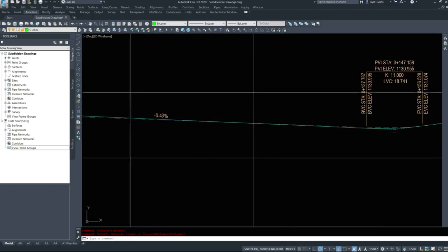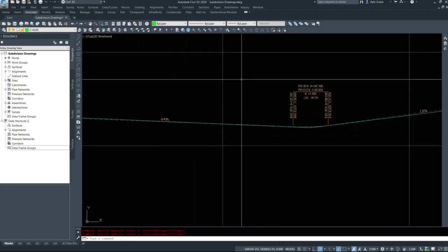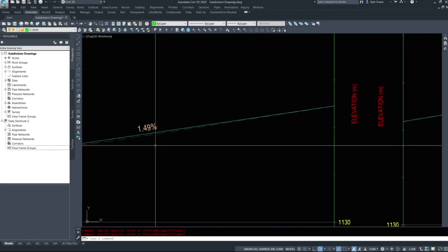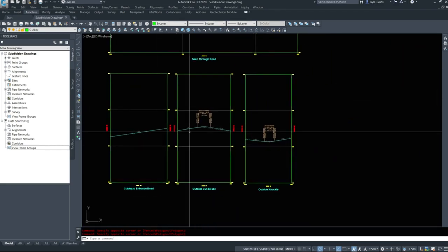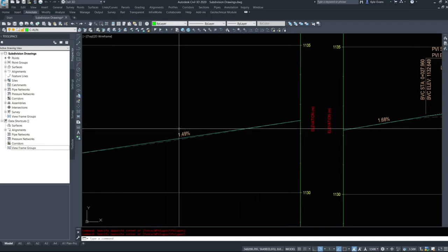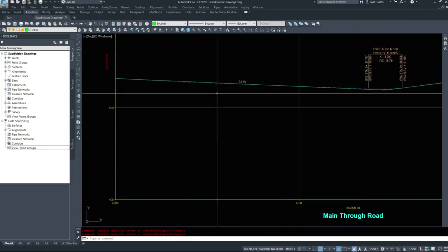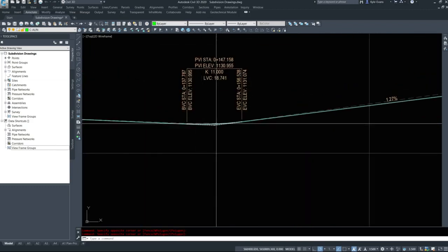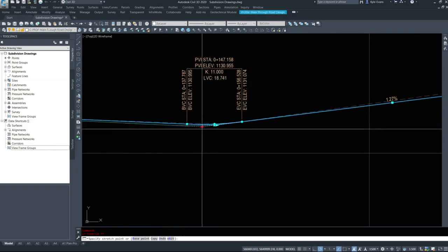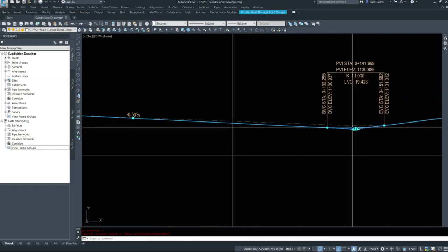Like the highway design, we also have to match minimum slopes and maximum slopes for the City of Calgary. However, maximum slope is a lot greater. We can go up to 8 to 12%. Minimum slope, I believe we still have to be 0.5%. So this doesn't necessarily work. So I'm just going to move my PI.